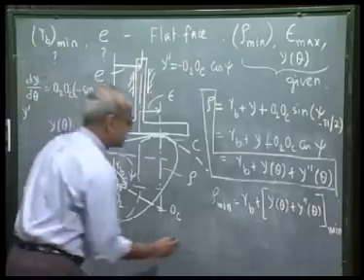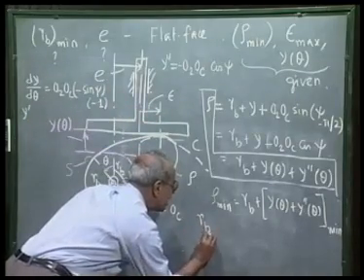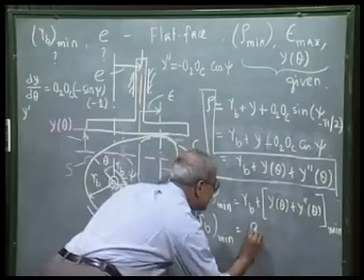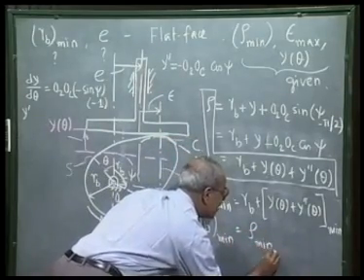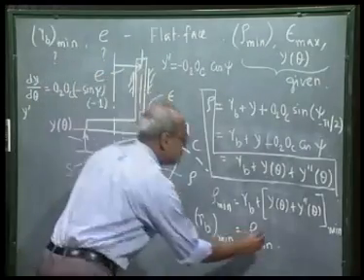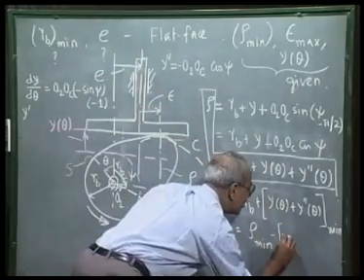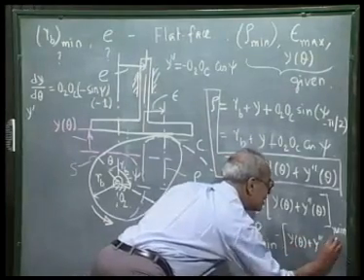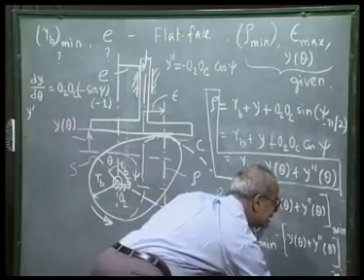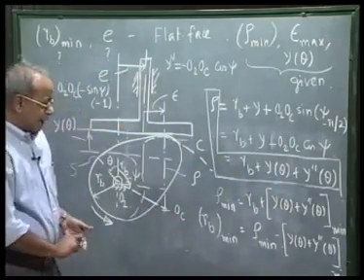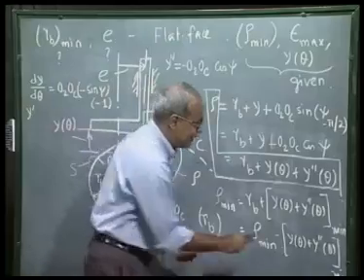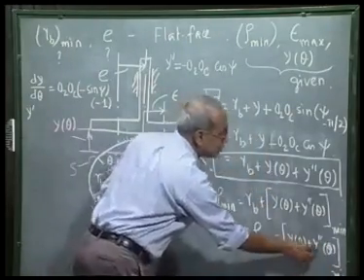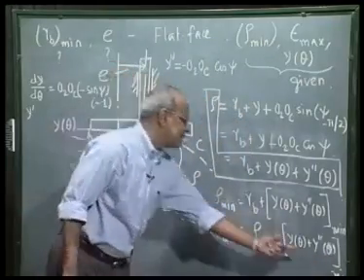So that clearly tells us that the minimum value of RB has to be given value of rho min minus y theta plus y double prime theta. I have to calculate the minimum value of this expression. For a given value of y theta, I first find for which value of theta y theta plus y double prime theta is minimum, and what is that minimum value.